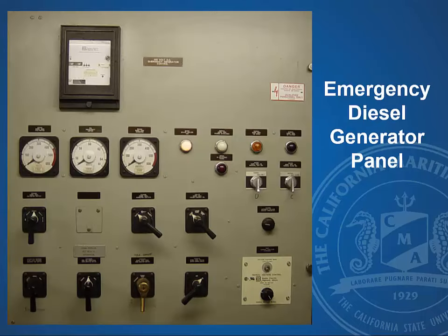Then this is the board. You have your voltage regulation down here. You have your watt meters, watts, volts, hertz for frequency, and you have your controls for the generator itself. This guy down here, this is for the feedback feature. And again, there is a key that goes in that to disable it, because when you disable this, you are disabling a vital safety interlock. And again, the Europeans actually disagree with Americans. They do not have this feature.